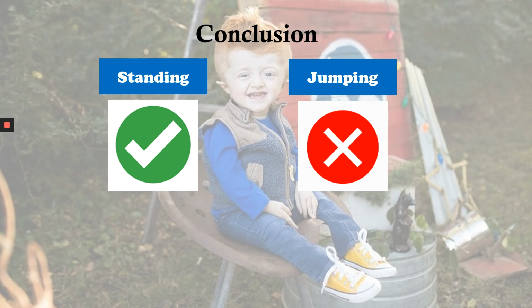The three models of the tibia were generated by software based on the CTs. The key parameters of the FE model, including boundary conditions, mechanical properties of the materials, and the geometry parameters, make an important contribution to the accuracy and reliability of the analysis. In addition, the fracture risk of each daily activity was also investigated based on the maximum bone von Mises stress generated.